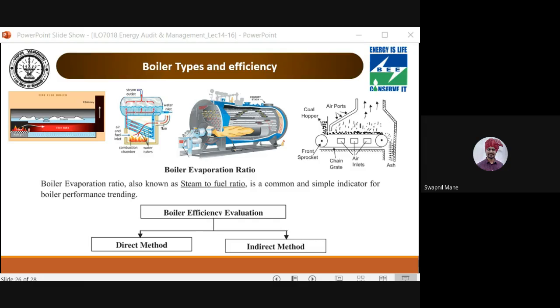So even though the fuel used is solid fuel, with the help of this air which is coming from the bottom at low velocity, and then gradually increasing this velocity, each and every particle will come across this firing range, right? And this bed will become fluidized, and that is called a fluidized bed boiler.